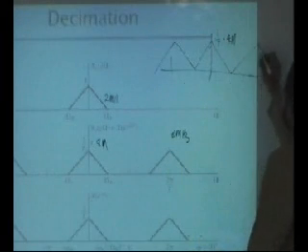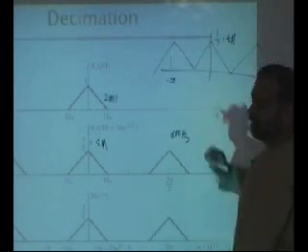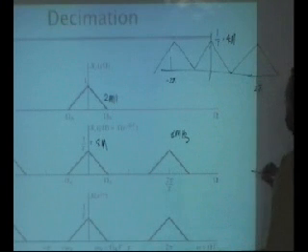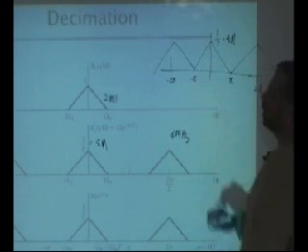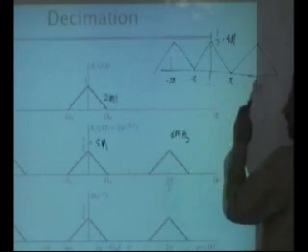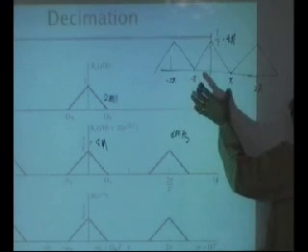In this case, the sampling frequency is still going to be 2 pi and minus 2 pi, we know. But what about this? This is going to be at pi, and this is going to be minus pi, right? So if you are sampling appropriately, your highest frequency will always map at pi and minus pi, always. So this is where you are not spending any extra samples to capture a signal.